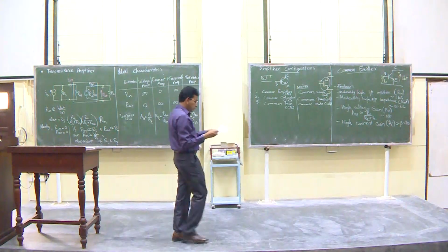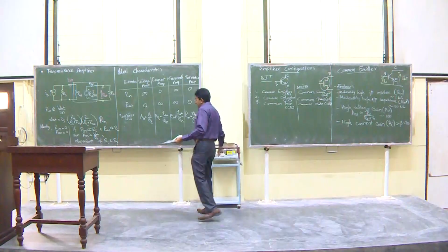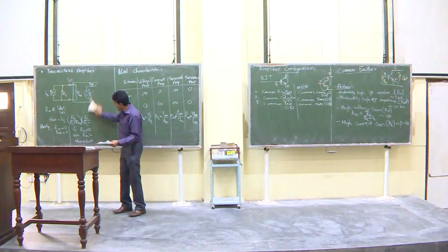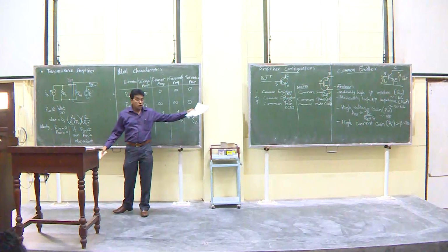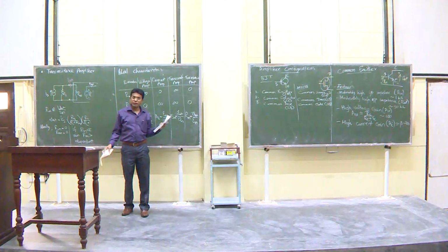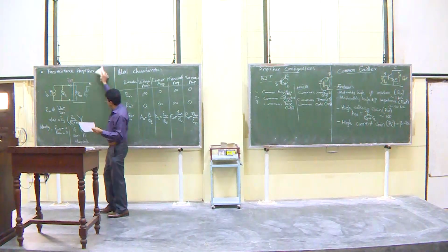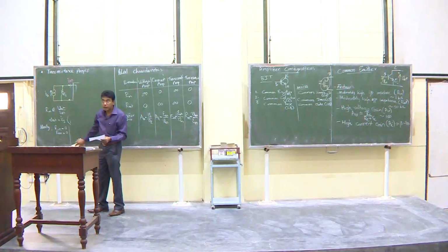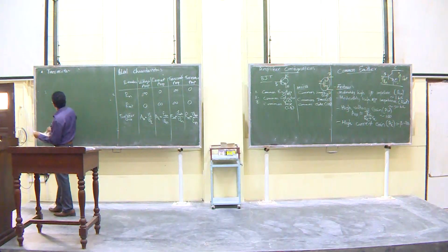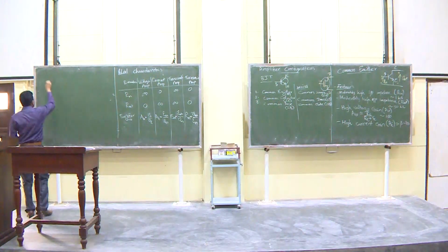Okay. Large power gains are achieved. Now, if I draw an example circuit, this is basically what we have been looking at actually. Because of this property, the most commonly used BJT amplifier configuration is the common emitter amplifier, because we mostly use these things to gain power, and this has the largest power gain. So, we can look at an example.